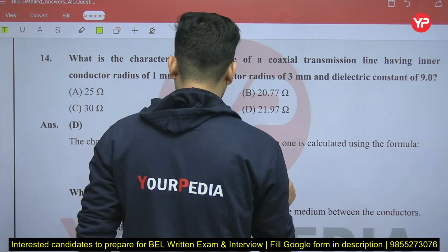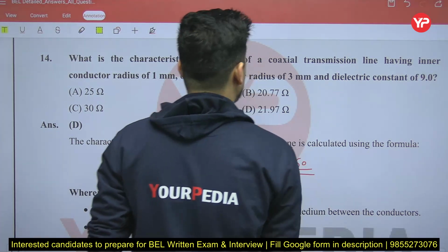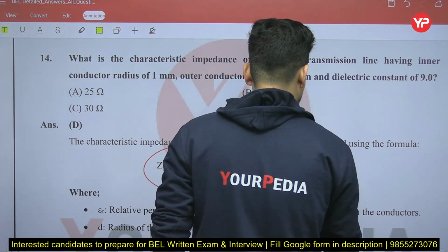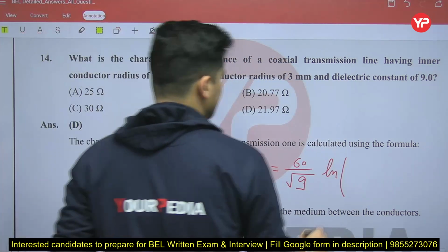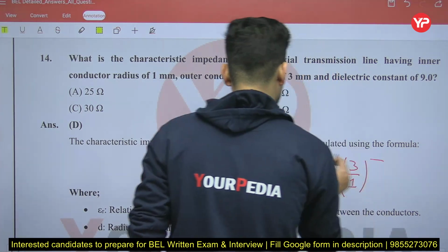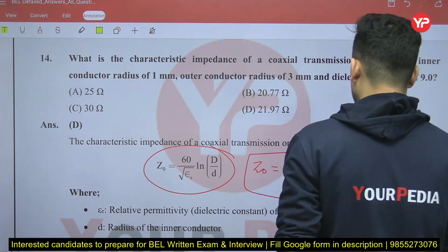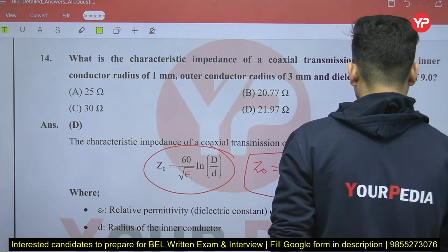Z naught is going to be 60 divided by under root of epsilon r, epsilon r is 9, ln D by d. D is the outer dimension, that is 3, divided by 1. When you put these values, what we get here will be 60 divided by 3 ln of 3.